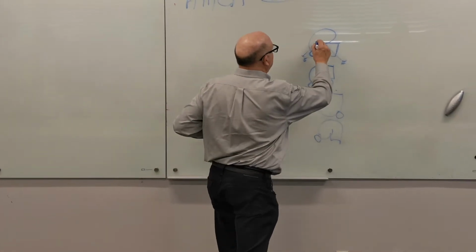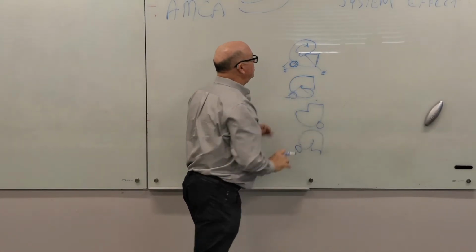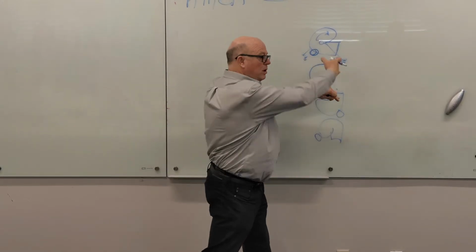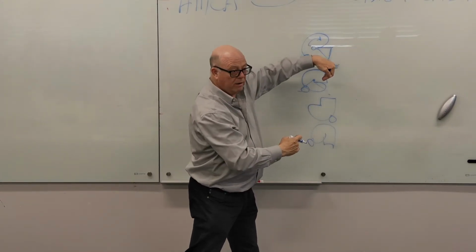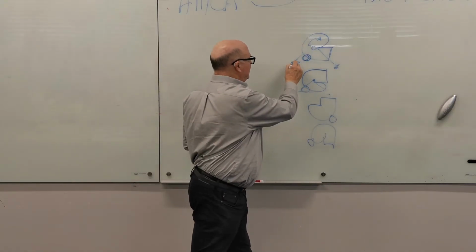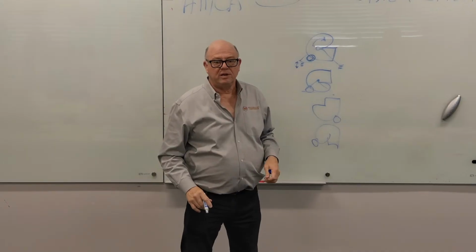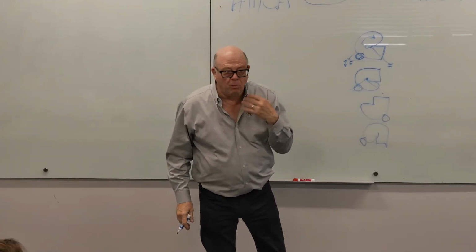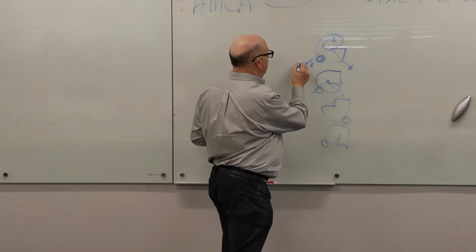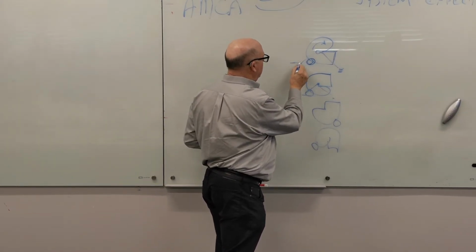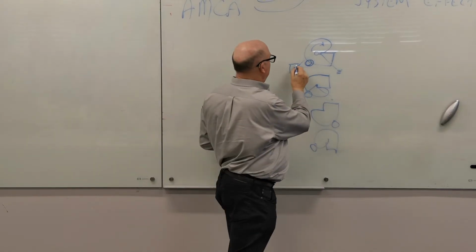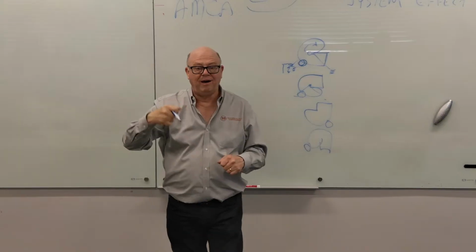But it's going to be also different for the manufacturer based on the rotation, because when that thing starts, it pushes down on this one and the one on the other side, right? And it also tends to stretch this one. You might even, in a really high static application with a lot of start torque, have a snubber here that acts to hold the frame down with a little rubber donut in there.